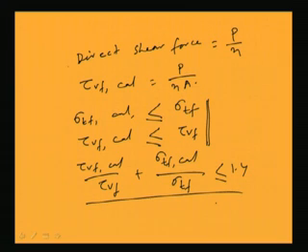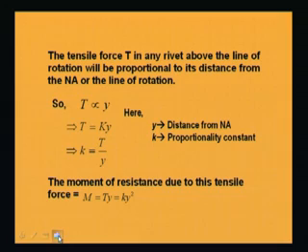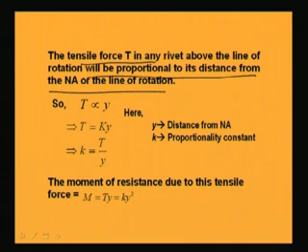So, in this way we can find out the extreme rivets which are getting the maximum stresses, and whether it is more than the allowable stresses or not. So, let me summarize once again what we have seen. First we have considered that the tensile force in any rivet will be proportional to the distance from the neutral axis of the line.